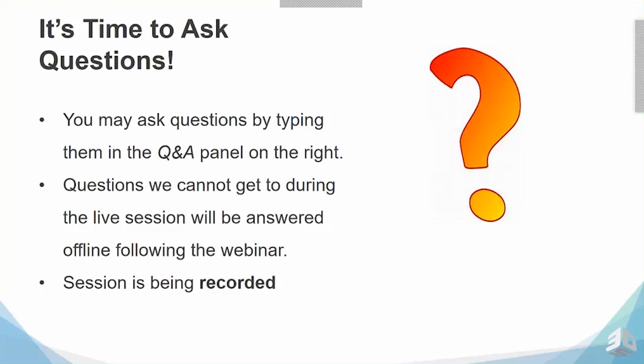Okay. Actually, the questions are really rolling in here, Rocky, so I'm just going to get to the next one. There's a few about material. What material did your analysis run with, and is it possible to perform the analysis for composite materials or perhaps some polymers? So I know we were talking about metal here, but let's answer that one. So I ran mine with Ti 6-4 Grade 23, and that's pretty typical of a lot of the healthcare stuff. Low oxygen, pretty stiff material as far as titanium goes.